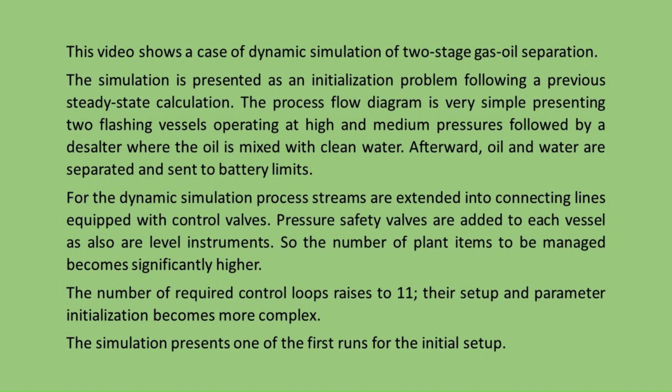The process flow diagram is very simple, presenting two flashing vessels operating at high and medium pressures followed by a desalter where the oil is mixed with clean water. Afterward, oil and water are separated and sent to battery limits.